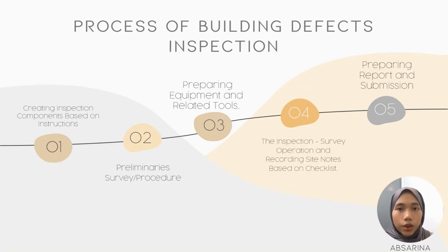It must also ensure both external and internal inspection, such as the building frame structure, quality of building, electrical and mechanical systems and also the installation. Last step is preparing the report. All the significant data types, images, factors and any additional information must be included in the report. All parts of the selected property must be inspected methodically to ensure no surface is missed. So the client will receive a completed report with fulfilled criteria of inspection.